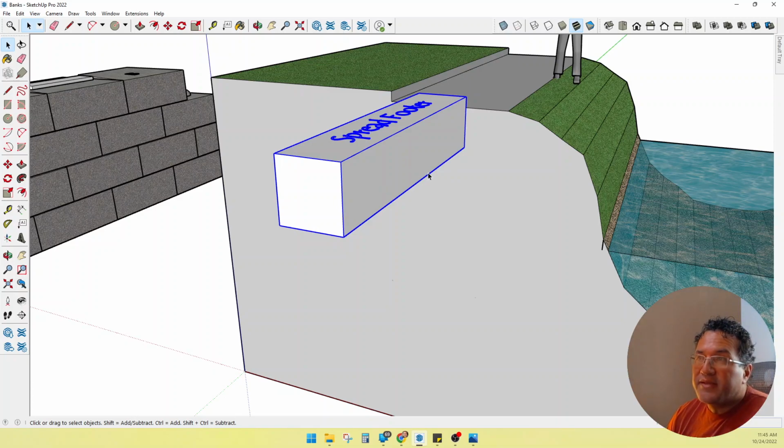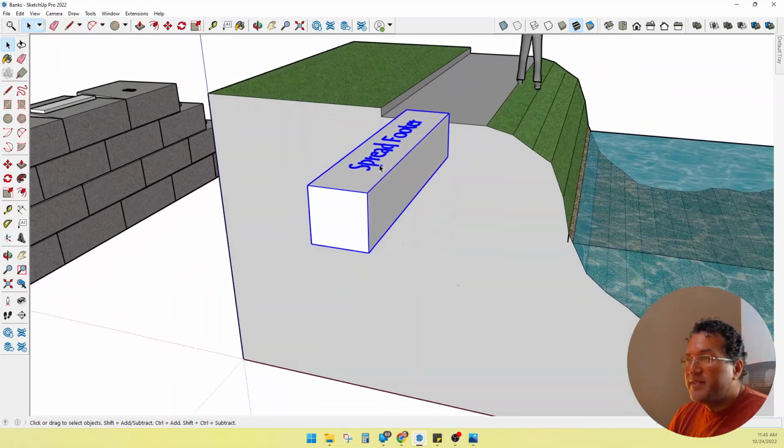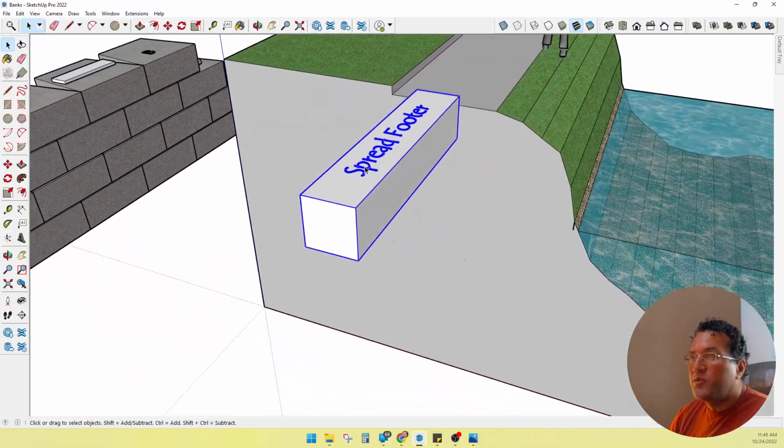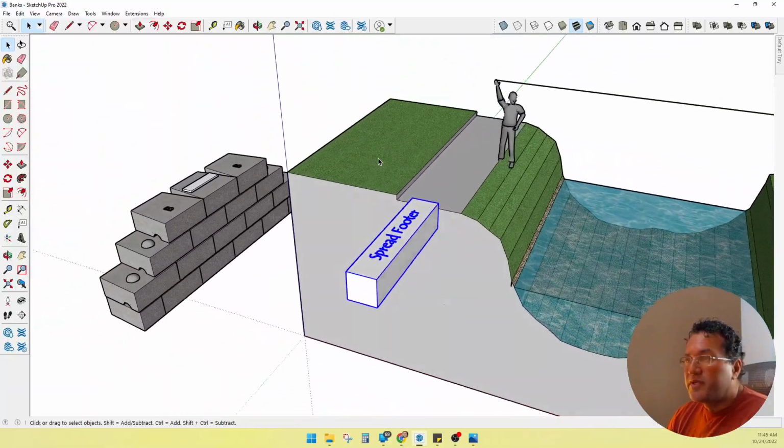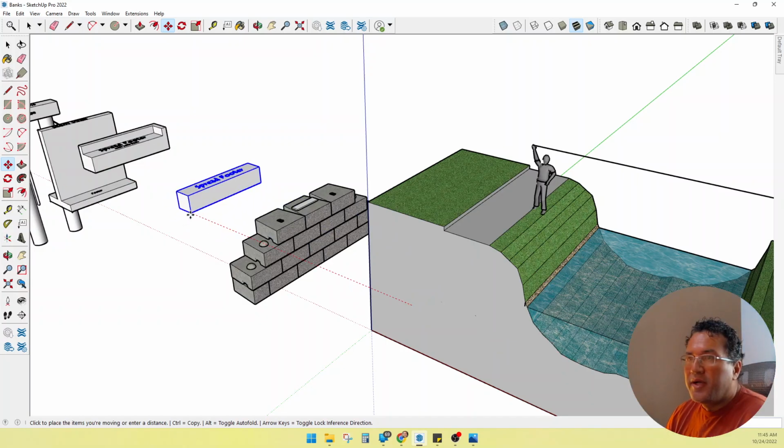Alternatively, you can always excavate, add gravel, angular gravel, nothing round, and then build your spread footer on top of that. So either one is fine. Spread footers are pretty inexpensive, and a lot of concrete guys will build these spread footers because they're just so simple to build. The next option that's going to be slightly more expensive, not a whole bunch more, is going to be a spread footer.